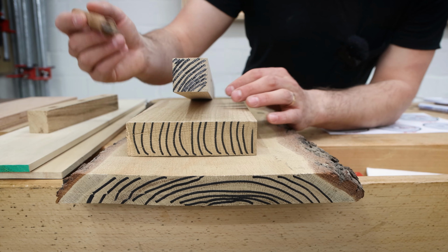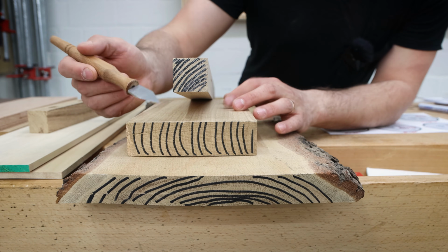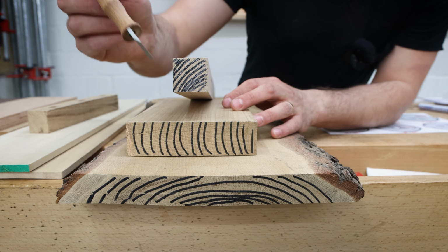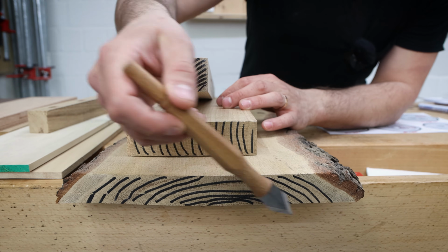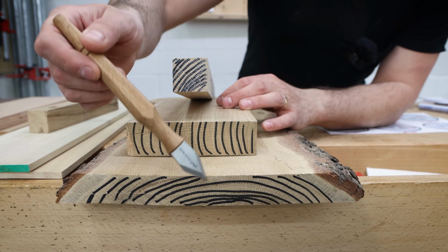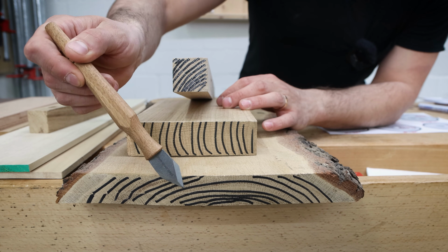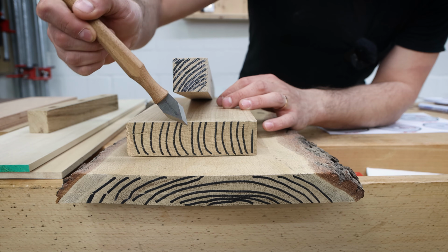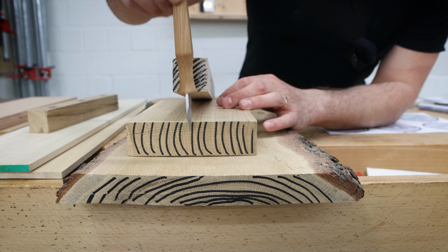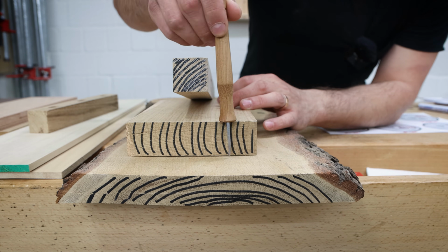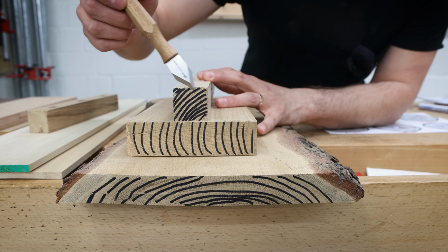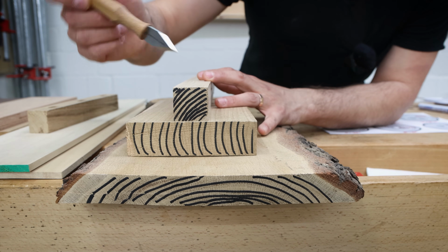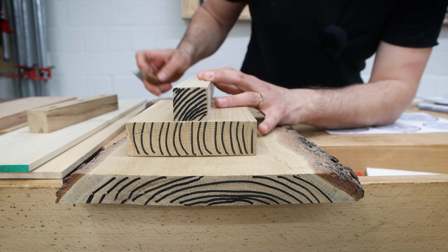To identify which cut the board has, you can look at the end grain. At the end grain, you can tell the fastest. Here you can see the growth rings are running at a slight angle, so this is definitely a flat sawn board. Here, the growth rings are running almost 90 degrees to the face side. This means that's a quarter sawn board. And here you can see the growth rings are running perfectly diagonal, and this is a rift sawn board.